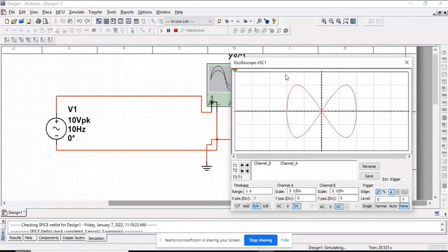So the value of VT is 1 and HT is 2. And the fx means input frequency. So you can calculate, 2 by 1 into fx. So 2 by 1 into 10, you will get 20 hertz. That is the value of output signal.